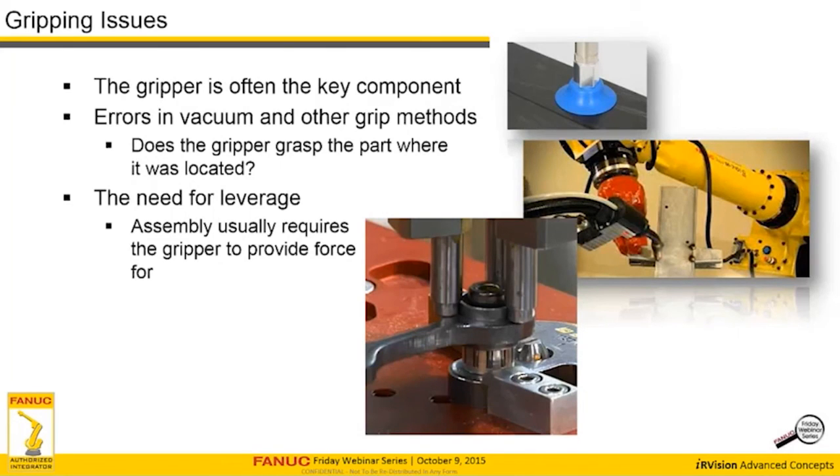We like to grab parts with vacuums, and I have seen people attempt to do assembly applications using grippers that are just vacuum grippers. Here's the problem when we talk about this in terms of high precision, highly precise assembly applications. Vacuum grippers, by their nature, introduce error at the point of grip, particularly for light objects, particularly for smaller objects. We can show you high-speed video and other examples of how this happens.